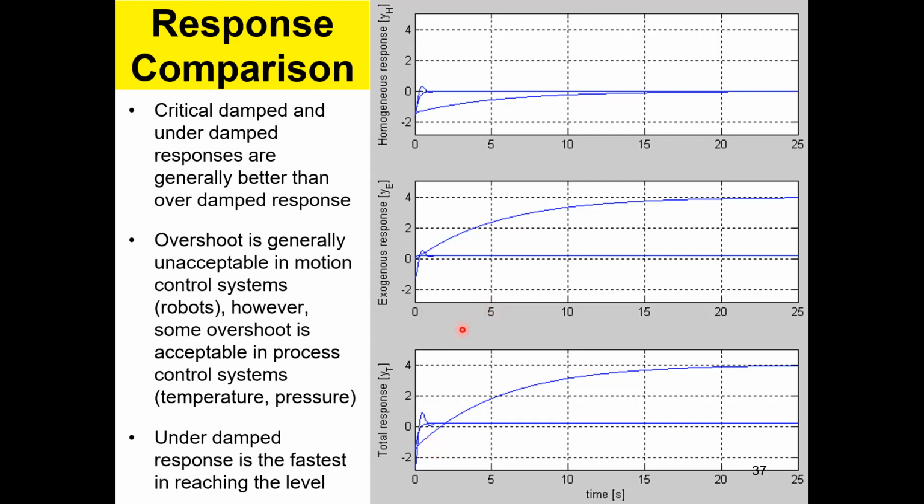So we can see a lot of analogy here in control systems. If you study very well, you can relate some of these things to society also. On the other hand, the critically damped case is very quick. With very little energy, you move from A to B, right? This is the fastest and the safest. And the oscillatory one is fast, but it goes up and down, which means you go this way and the other way, and this way, other way, and eventually you get to the place, which is not very efficient, right? But it is better than the overdamped system.